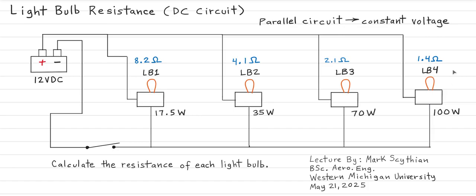So let's just say that did happen. You could rule out the circuit as being discrepant. You could ignore it. It's not discrepant. And then you go across, take the multimeter reading on light bulb 3 positive to negative, and you get 2.1 and so on and so forth. So you may have some other issue like a switch to ground, or perhaps there's nothing wrong with the circuit.